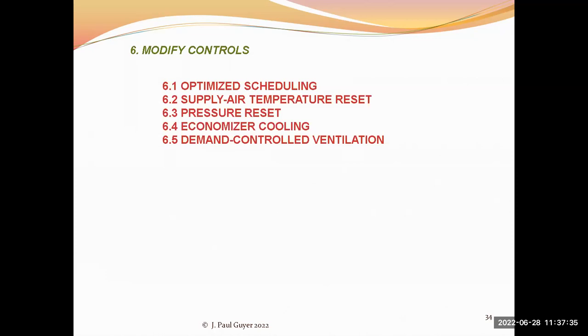The quantity of outside air that is brought into the building for air quality control purposes has been specified in the ASHRAE guides and so on and so forth to be typically so many CFM per occupant in the space, or so many CFM outside air per square foot of the occupied space.